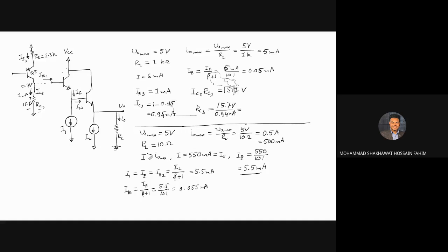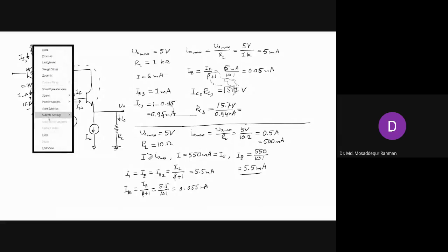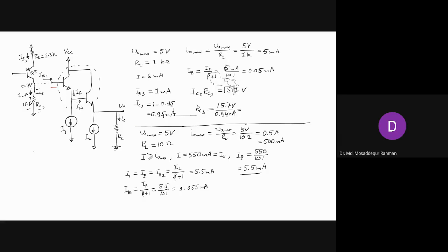So now we have left our dependency on the RL, right? Right. Because the input resistance for this Darlington pair is very high, right? So the resistance that you see here, that is Ri, the output stage, that is very high. So that will be almost independent of this RL. And this is our Darlington pair you'll be using, right?